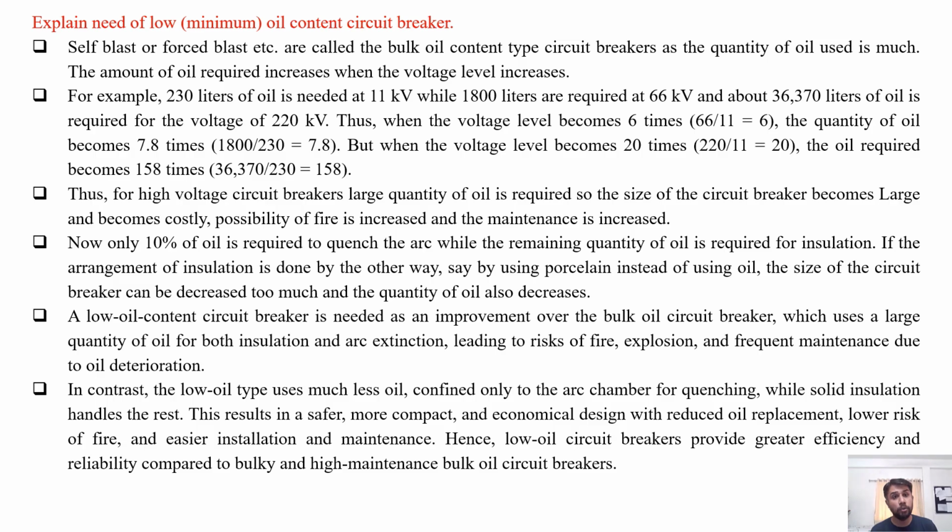In contrast, the low oil circuit breaker uses less oil, confined only to the arc chamber for quenching, while solid insulation handles the rest. This results in a safer, more compact and economical design with reduced oil replacement, lower risk of fire and easier installation and maintenance. Hence, low oil circuit breakers provide greater efficiency and reliability compared to the bulky and high maintenance bulk oil circuit breakers. So these are some points to consider the need of low oil content circuit breaker.